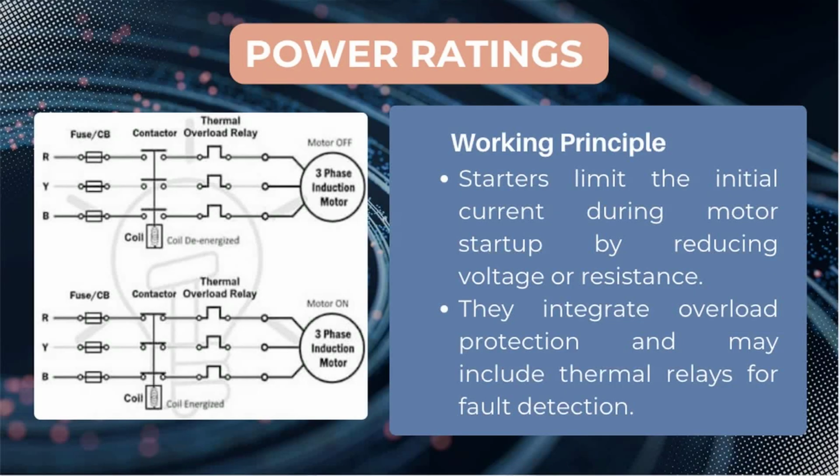Working principle. Starters operate by limiting the initial current during motor startup. This is achieved by either reducing the voltage supplied to the motor or introducing resistance into the circuit. Most starters also integrate overload protection, which is often provided through thermal relays that detect abnormal current conditions and shut off the motor to prevent damage.